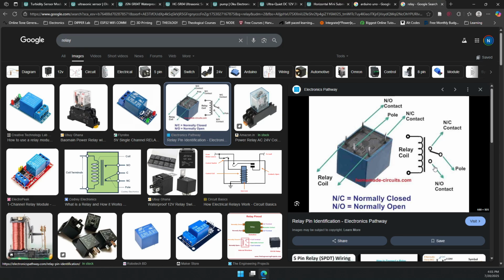So take, for example, the 12-volt pump. Let's say you have a 12-volt power supply. So you're going to bring in a 12-volt power supply, all right? But now you want to control its turning on and off. One way you can control a 12-volt power supply to a pump is by manually turning it on and off. But you want that control to be done by the microcontroller, right? So we are using something that, when it energizes this relay coil, the switch is going to be at one position. When the relay coil is de-energized, that is switched off, it moves back to a default position. So simply turning this on and off is going to toggle the switch position on and off.